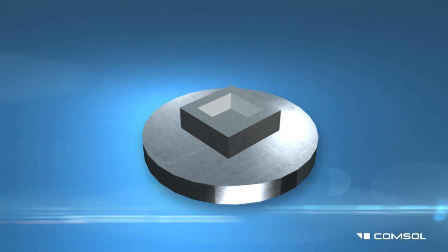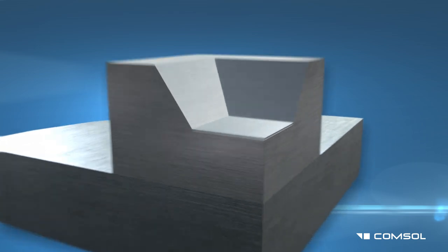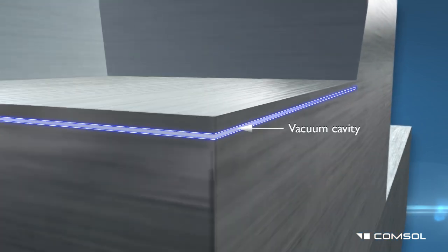Today we will be simulating a capacitive pressure sensor, both with and without stresses induced by the packaging. The geometry of the sensor is symmetric, so only a single quadrant is modelled. The sensor consists of a thin chamber sealed under high vacuum, acting as the dielectric in a capacitor.